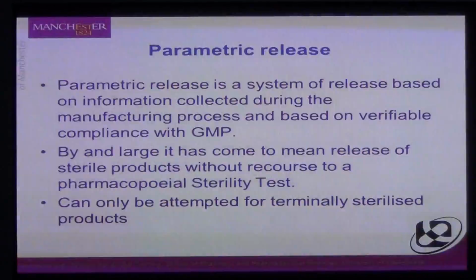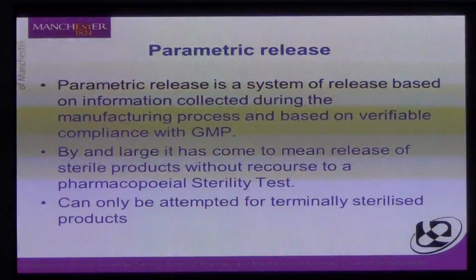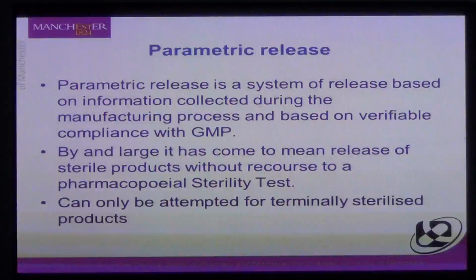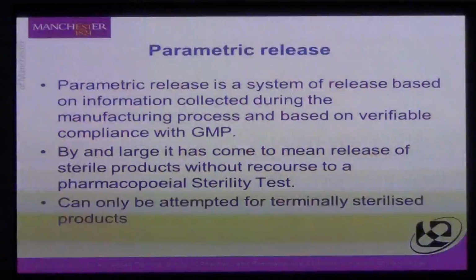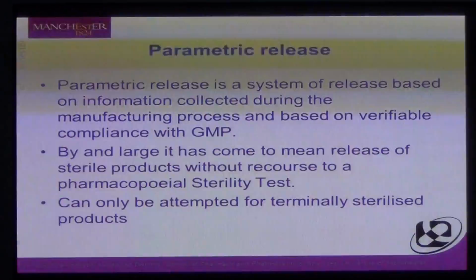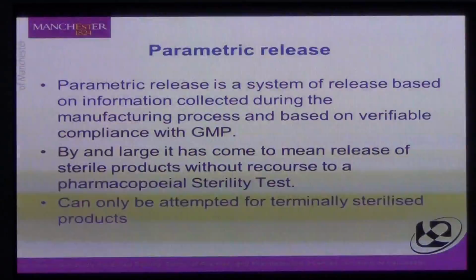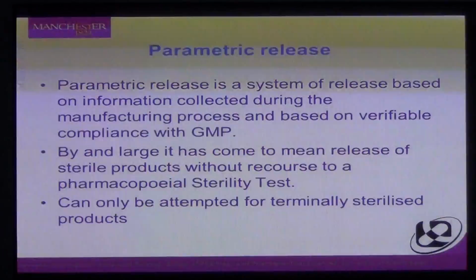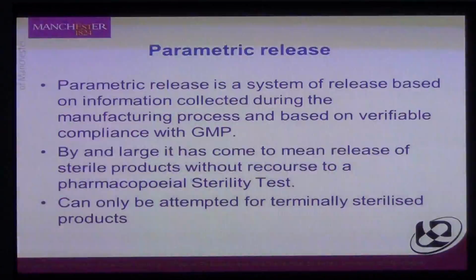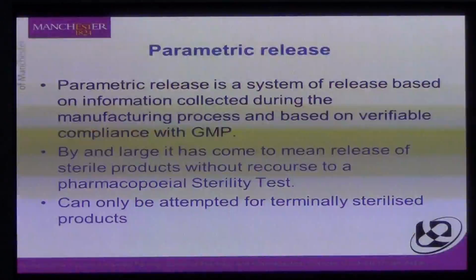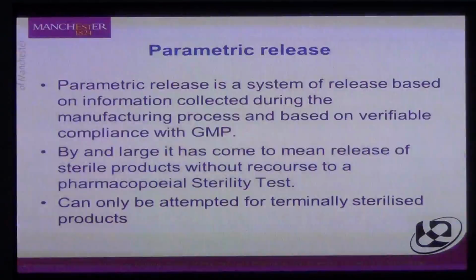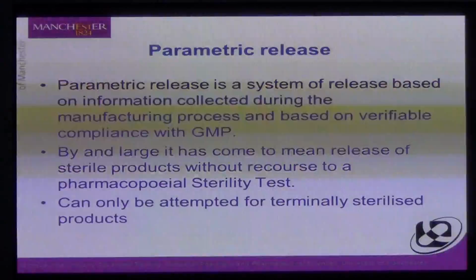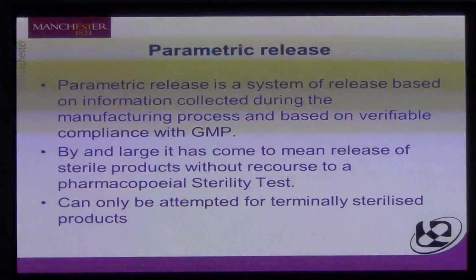So it means collecting lots of information about process controls, with things at the right temperature, with products mixed for the right length of time. It's also about collecting lots of environmental monitoring data. Importantly, it cannot be used for aseptically filled products, and to make the case for parametric release, the case has to be made to a regulatory authority.